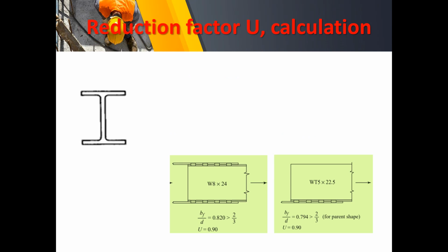So just remember that on a wide flange, this is our width of the flange, and this is our overall depth. And so here will be the web. I'm sorry, it should be the flange. So the outer fibers are what we call flange. And the stem of the section is actually the web.